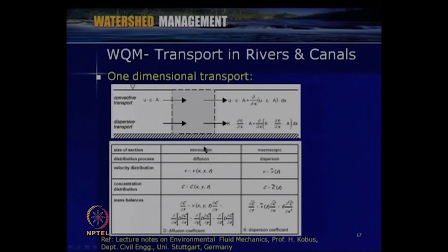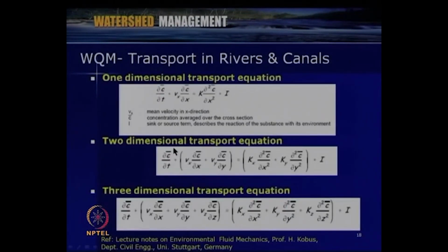Like size of section, microscopic or macroscopic. These details are taken from the lecture notes of Professor Kobus, Department of Civil Engineering, University of Stuttgart, Germany, from the course notes on environmental fluid mechanics. Like a distribution process, diffusion, we have to consider this, which is coming from Fick's law, and then macroscopic dispersion. All those things we have to see, and the advective transport behavior also within the system we consider.